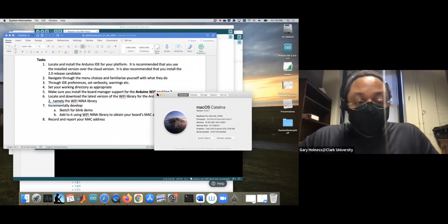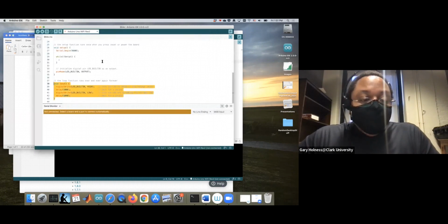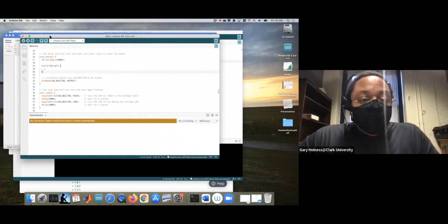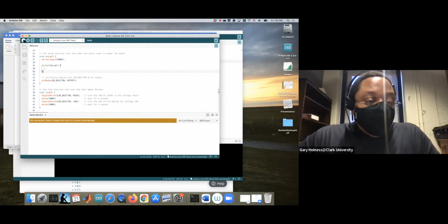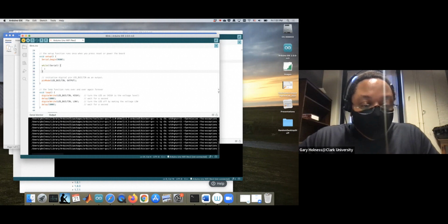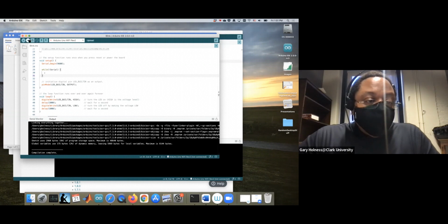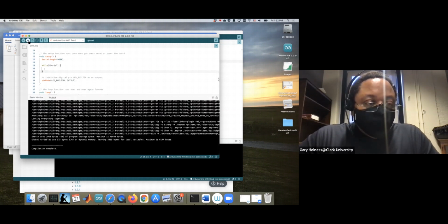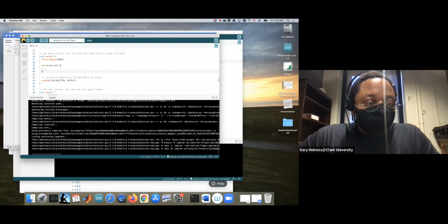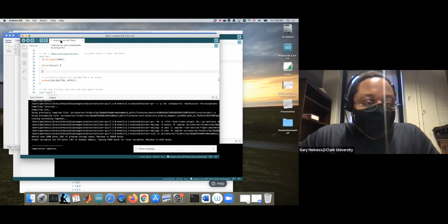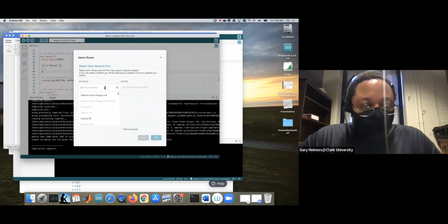So the next thing we're going to do is upload this sketch. After compiling it, we're going to upload it to the board. And so I'm going to click verify or compile, and we see some outputs, compilation complete. And now I'm going to do my upload. Oops, forgot to load the board. So here, select another board, Wi-Fi revision 2, show all ports.